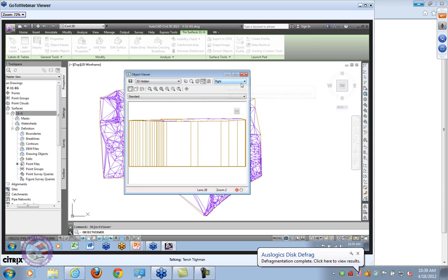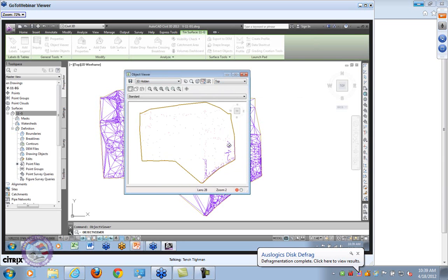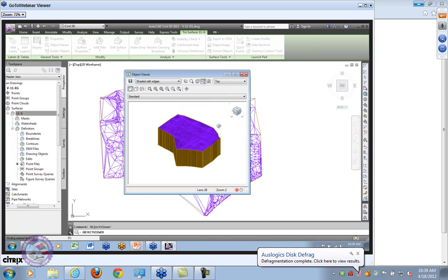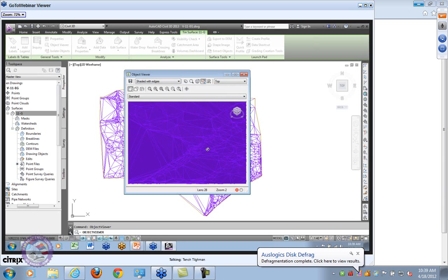Once again, we got this view-based thing, and then we got this visual style thing that is always sitting there too. So, we can go shade it with edges here, okay? And AutoCAD is now expressing the style itself. I'm going to move the camera around and we're going to zoom in here in a totally different way. So we got layers of this. There isn't just one view.